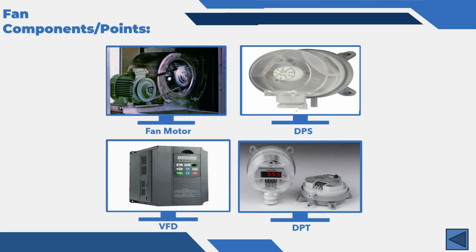Fan components. Most fans consist of these components, which are connected to the BMS system: fan motor, VFD (variable frequency drive), DPS (differential pressure switch), DPT (differential pressure transmitter).